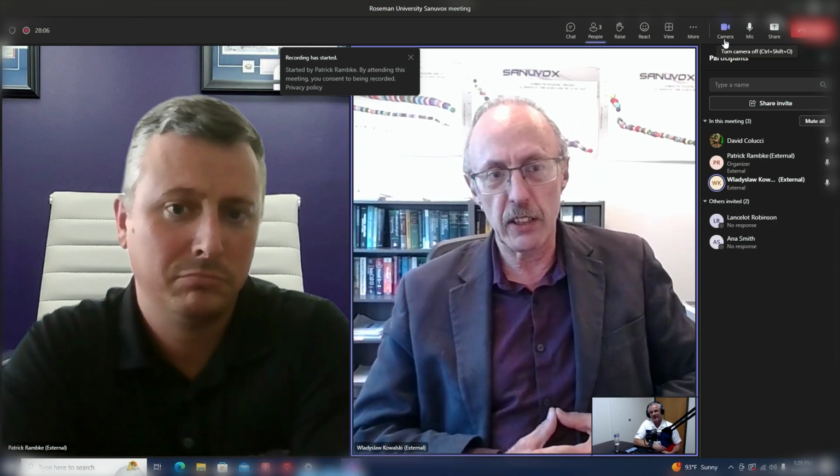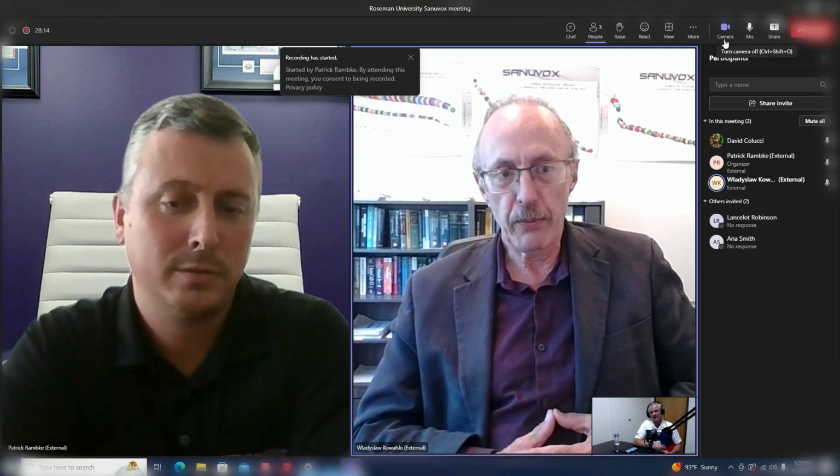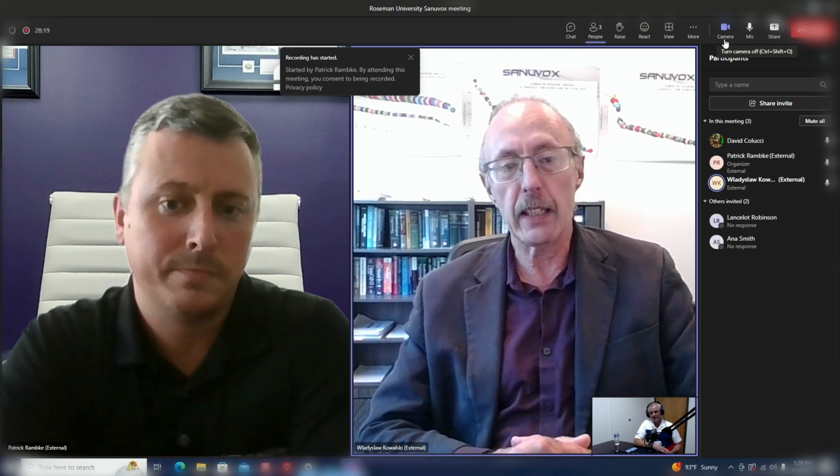Instead of putting 6 air changes per hour with big fans and ductwork, we can put in, for example, upper room units in all the rooms and not boost the airflow at all. And we will still get high performance. Therefore, we can both decarbonize a building and clean the air at the same time. It's not impossible. It's just a matter of engineering the right systems to do that.